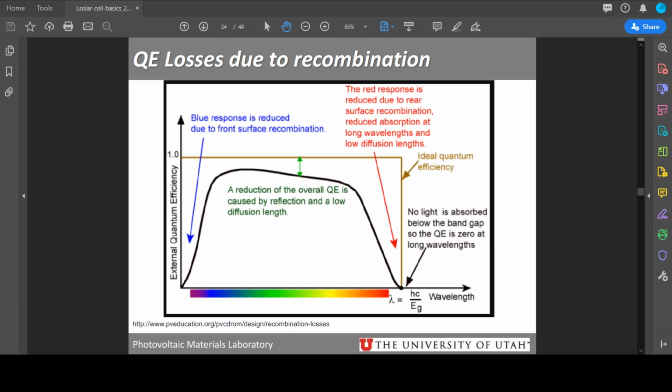Yes. So this is the effect of a shunt resistance, and as you can see, as the shunt resistance goes down, you typically have a problem lurking there. So when I increase the shunt resistance to a very high value, I approach what you typically would expect in an ideal solar cell, where both these curves match. Similarly for the series resistance,